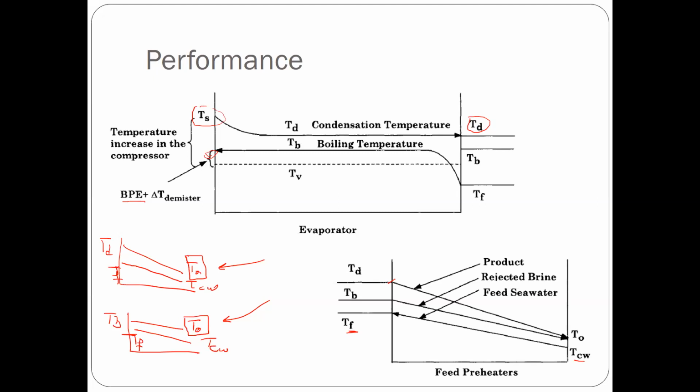the kind of advantages that we are getting from this unit. The disadvantages are basically the relatively high power consumption. We are talking about, at the best condition, 8 kilowatt hour per cubic meter, which is at least twice what you can get in a reverse osmosis right now. It is also twice what you can get in a multiple effect desalination system operating with steam.